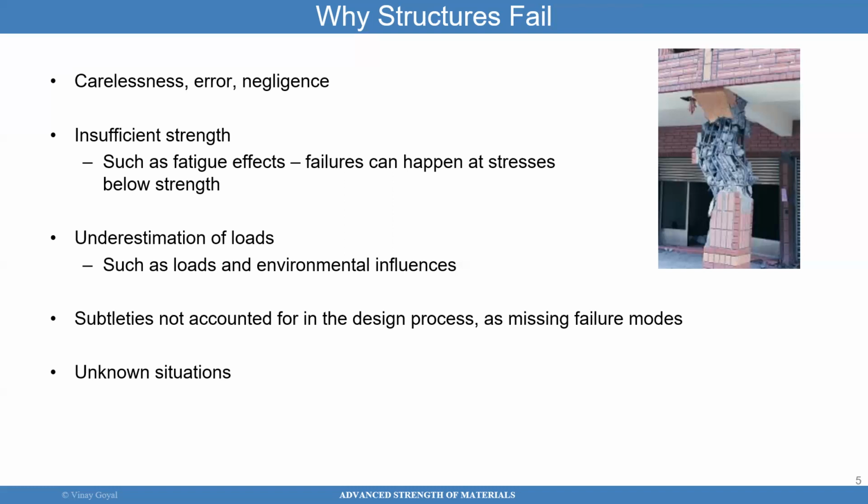But in reality, when the flight was instrumented and the telemetry was gained, it was determined that the loads were much higher. And some of the failures that have occurred in real life are because the loads were underestimated. And so that's why instrumentation during flight is quite helpful.